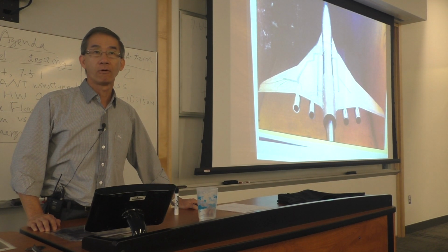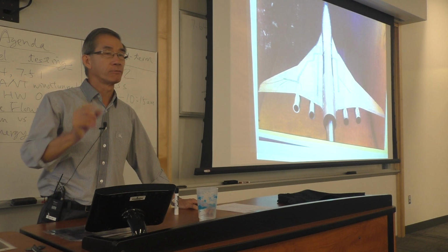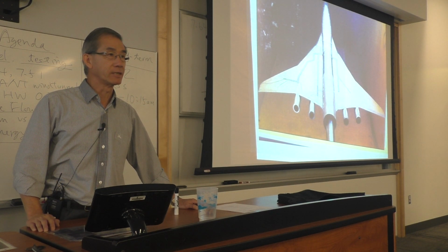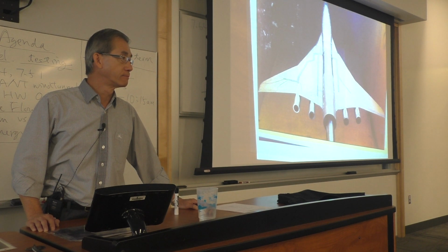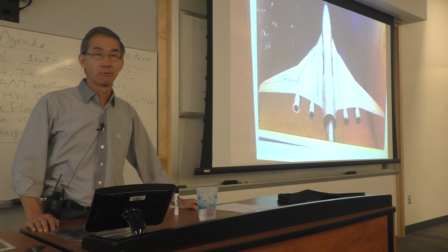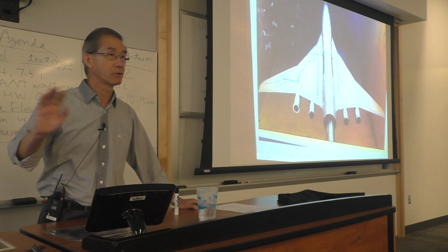What do those four tiny holes an inch from the nose of the probe read? What does the center port read? Stagnation pressure. What do those on the side read? Static pressure. Static pressure is the pressure undisturbed.